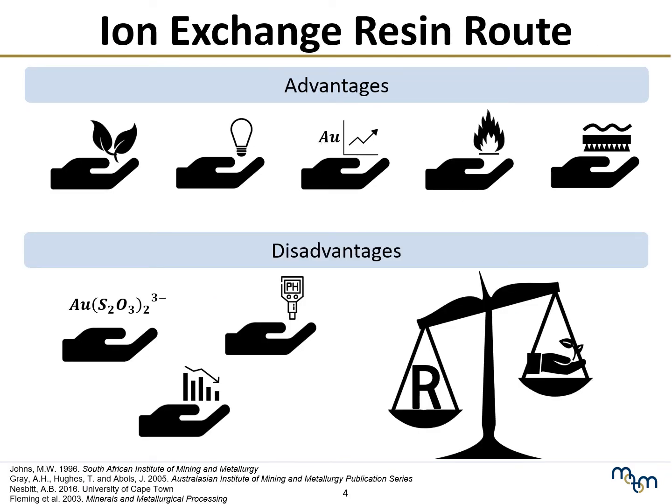So why ion exchange? There are many advantages and disadvantages to this method. Some of the advantages include that it is more environmentally friendly, no thermal generation is required and therefore it is energy friendly. There are higher loading capacities and loading rates associated with ion exchange. And in comparison to other processes such as solvent extraction, it is simpler and has the potential to be automated, including the fact that it is less flammable. And when compared to activated carbon, there is better selectivity and a higher resistance to abrasion.